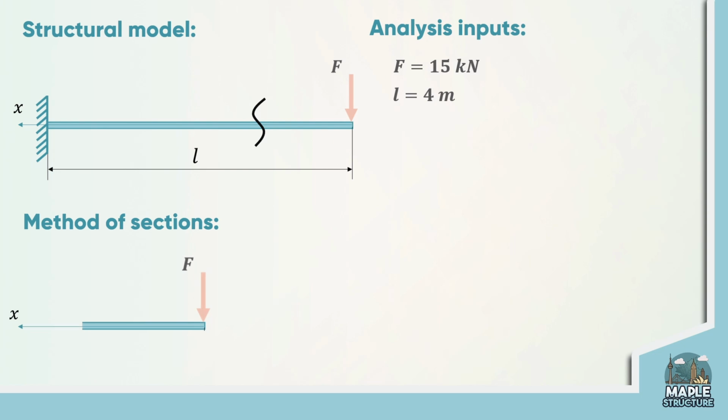Well, our system is in equilibrium, so it simply means each part of the beam is in equilibrium as well, and if we cut our beam somewhere, we must replace this missed part with internal force to keep the system in equilibrium. Alright, if our external force is vertical, it tries to bend our cantilever beam, so the internal reactions consist of 2 internal factors, shear force and the bending moment, and we have to figure them out by using statics rules. But before we go on, I'd like to clarify one small detail I haven't mentioned in my previous video. So why those internal reactions are directed the way they are directed.